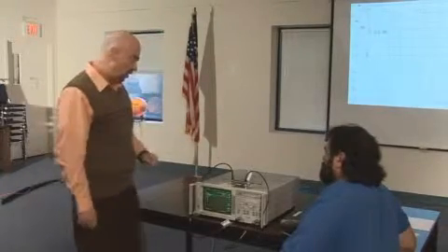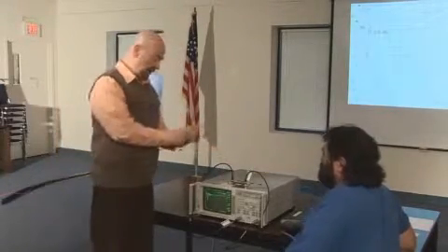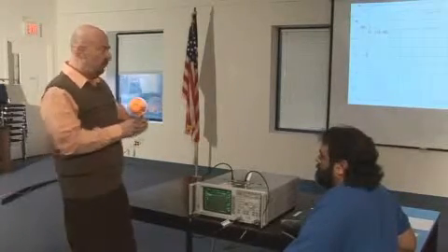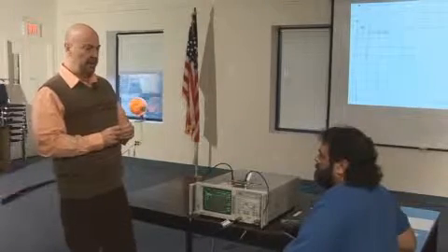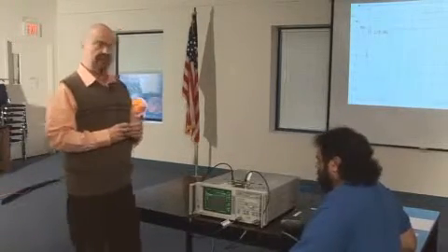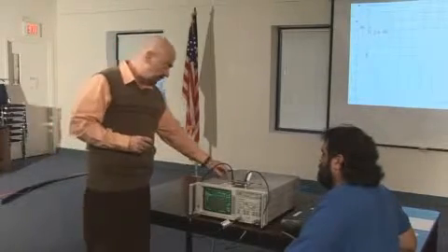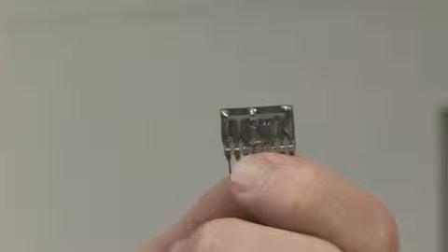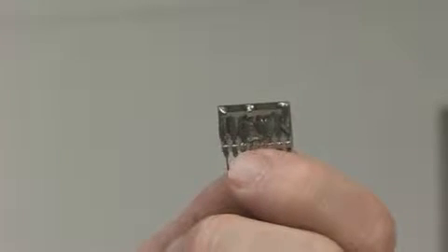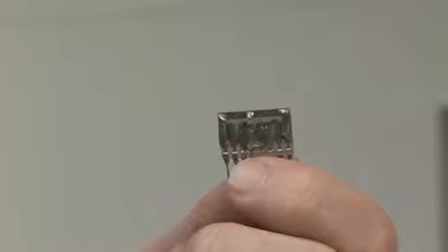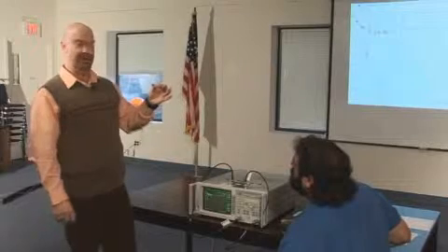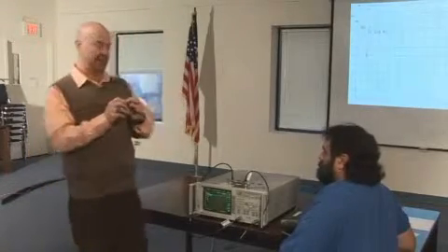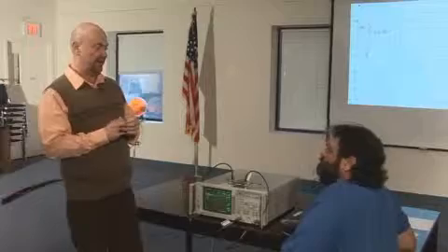To make matters even worse, chances are if they revamp the board you're using to incorporate this, they'll use a leadless type of part, a surface mount. By the way, in this type of device, a capacitor, you'll find that the axial leads are the worst because they're close. If you go to radial, where the leads come out the end, then you're in better shape. As a matter of fact, that is exactly what a surface mount component is: a radial where the leads are taken off completely and the ends of the body just form the leads of the device.